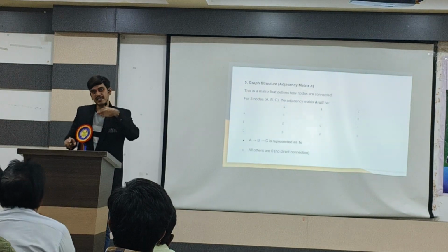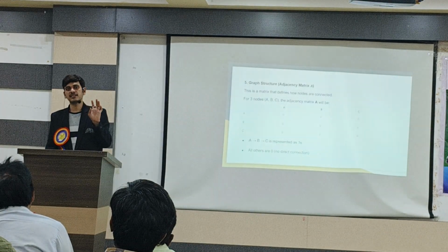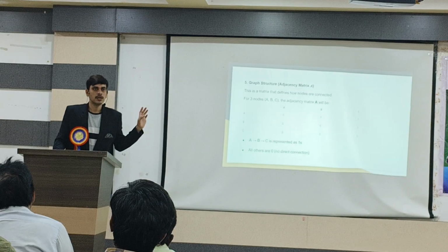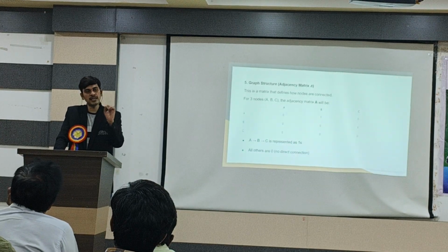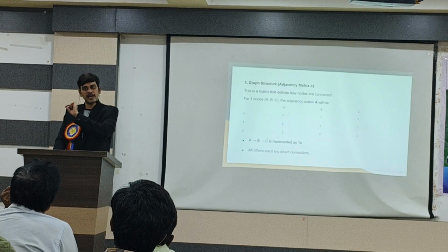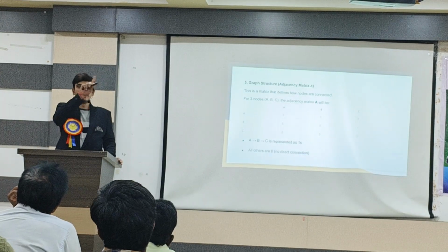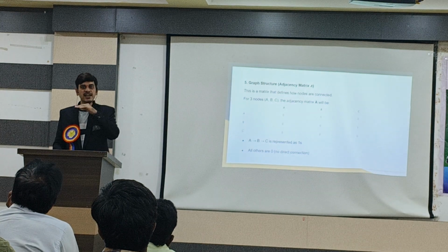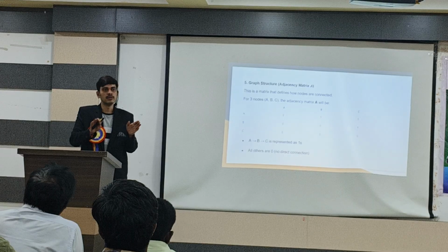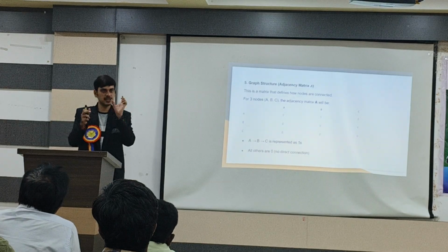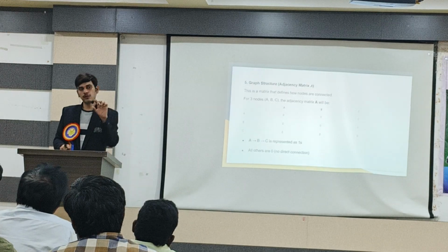So that at least the timing is checked at this stage. Once the placement is done, comes CTS, clock tree synthesis. Initially there won't be any clock. Once placement is done, at least the timing is checked. I told you timing is very important: if the timing is not met, you can throw the chip out. CTS builds different tree structures because the clock should reach evenly, since there is a difference between launch and capture delays. That's why useful skew is there.